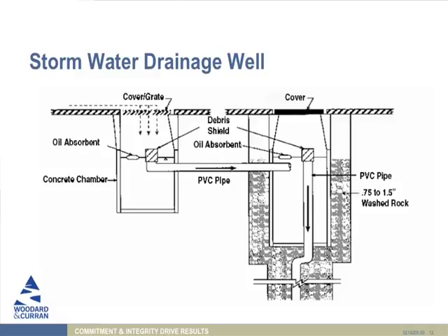Now, if you have a stormwater collection system composed of conveyances and catch basins that all ultimately have an outflow that go to some sort of water, that's not a dry well because you've got things connecting, you've got the water moving away. Here you happen to have two wells that are connected, but you can see the water comes into this well, goes from this PVC pipe into the secondary well, and then it just goes down into the ground from there. There's no outlet to either of these so that the water is being dispersed. So this is basically what a stormwater dry well is. It's a hole in the ground into which stormwater runs, and it's not anything elaborate. It's not receiving anything else other than stormwater, but it's considered a Class 5 injection well.